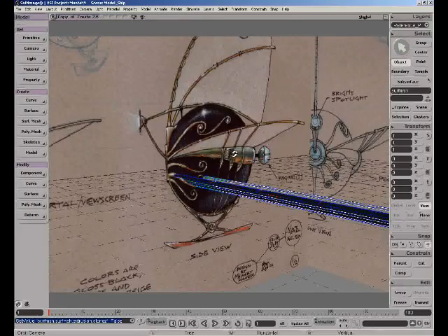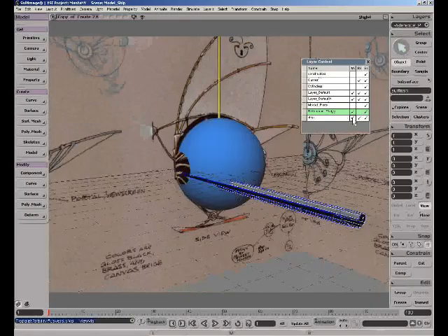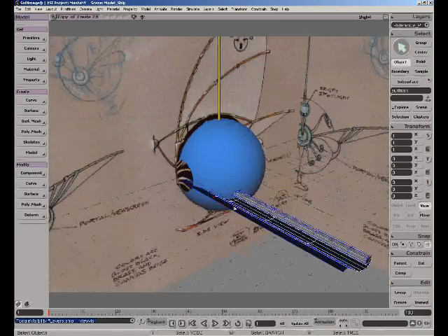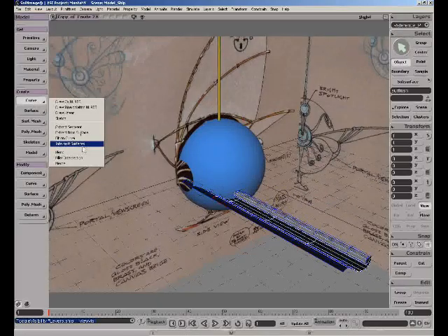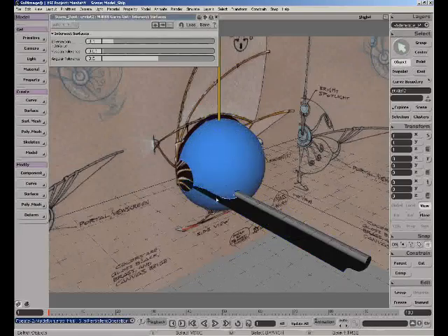And I'm going to go ahead and inside my layer tools here, unhide a layer called ship. And that really is just basically the hull of the ship and also this cylinder that's been stretched out. So we're going to use a tool now called intersect surfaces. So we'll just say we want to create a new curve where those two surfaces intersect. And the two surfaces are this one here and this one here. So we'll click on that. And now you can see right there, perfectly along the surface of that sphere, we have that curve.